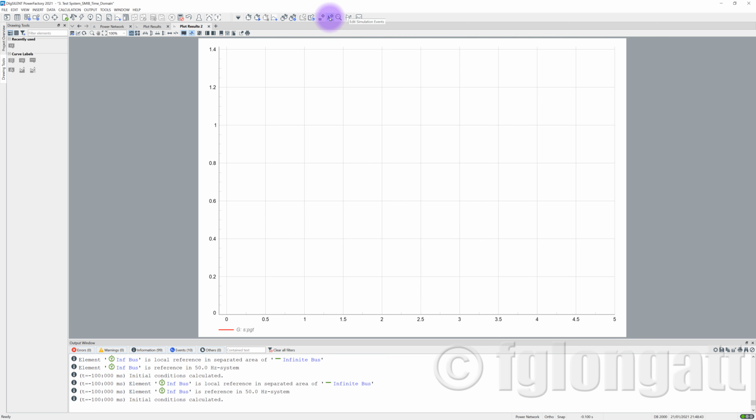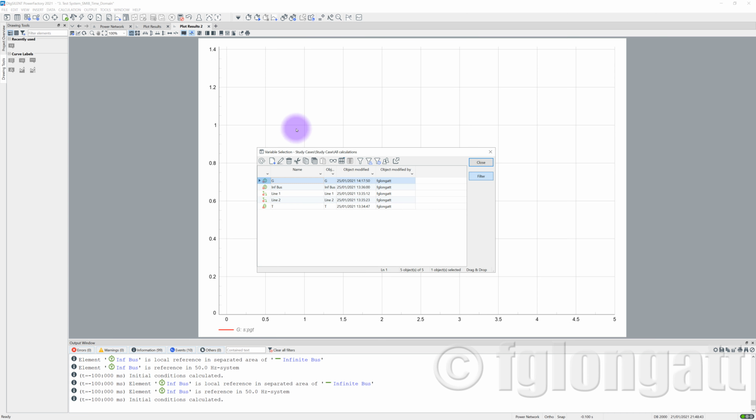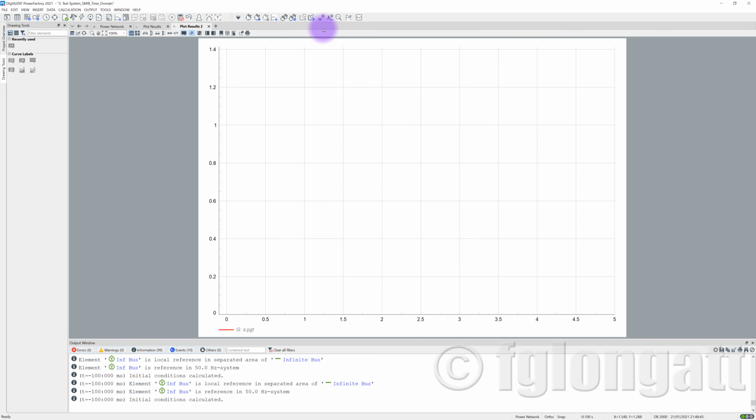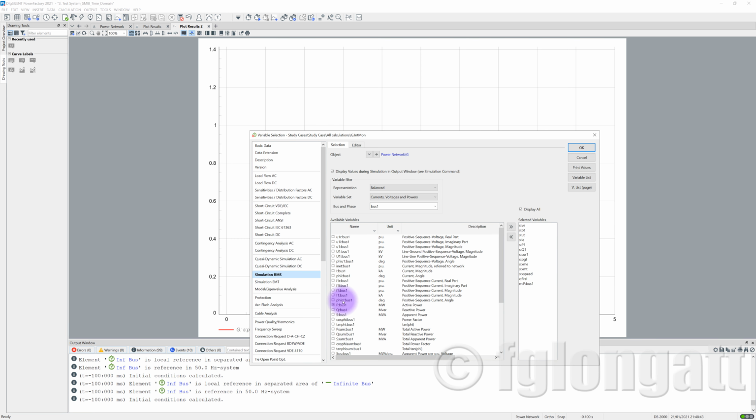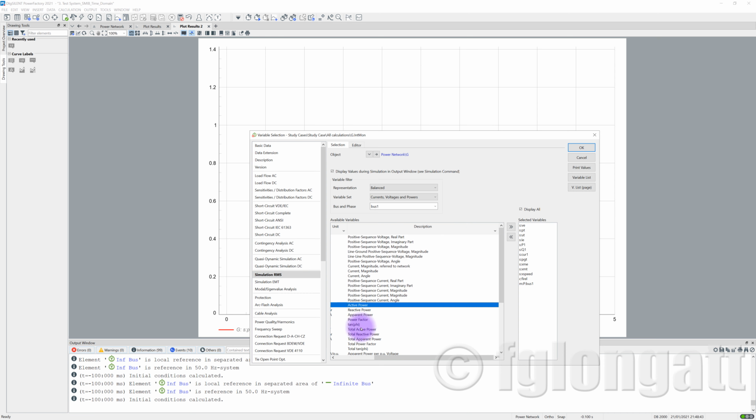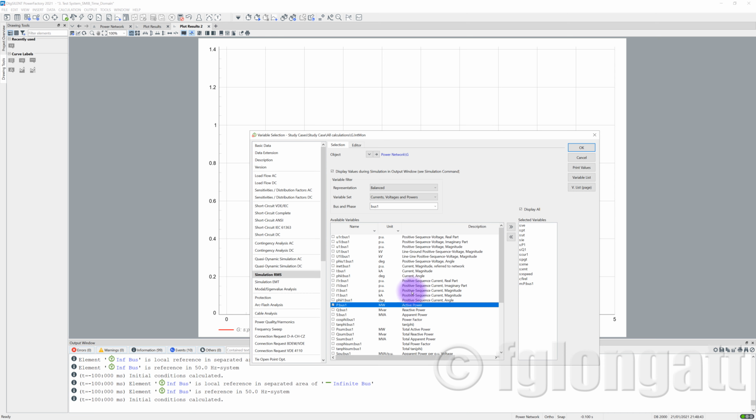Then I go here to this object here, okay? The result object, I select the result object, double click at the generator, and then select active power P. But this active power, I believe you can see that is defined in megawatts, okay? This is the one that I want to show you, okay? And remember the name because I will need this for the plot, okay?